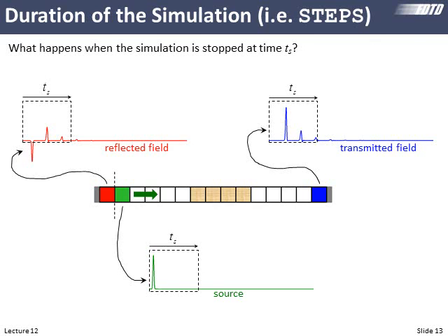But we can't run our simulation forever. Suppose we limit that. Suppose we only run our simulation for a time ts, and we just end it here. Essentially what we're doing is setting everything outside of here to 0 because we're not counting it in any of our spectra or anything. So we're just assuming it's 0 if we do that. So what are the consequences of that? We've calculated the stepped parameter with some specific number. No matter how big we make that, in principle, it will never be long enough. It needs to run to infinity to represent physical reality. So the question is, how long does that need to be that it's good enough for us?